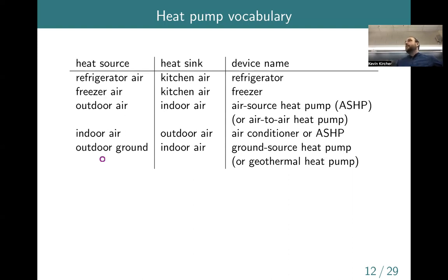So we saw that the efficiency of a heat pump depends basically on the temperature difference between inside and outside. And so if your outside temperature source is at 50 Fahrenheit rather than -10, you can imagine that your COP is going to be a lot higher. And so these ground source or geothermal heat pumps might hit a COP even on a really cold day of like 4 or 5, whereas an air source heat pump might be at like 2, 2.5. However, that improvement of efficiency comes at an increased capital cost, because to install a geothermal heat pump, you basically have to dig up your backyard and put a bunch of pipe down.